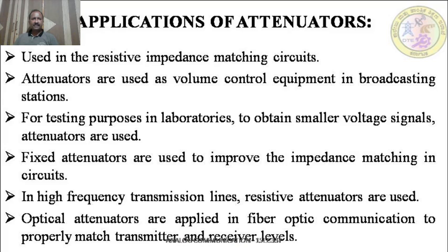The attenuators are used in resistive impedance matching circuits. Sometimes source and load are not matching each other. In that situation, you are going to use an attenuator to match the source with the load. Next, attenuators are used as volume control equipment in broadcasting. In almost all volume control applications, you are using attenuators. The attenuators are used for testing purposes in the laboratory to obtain a small voltage or a small current. You are going to use attenuators.